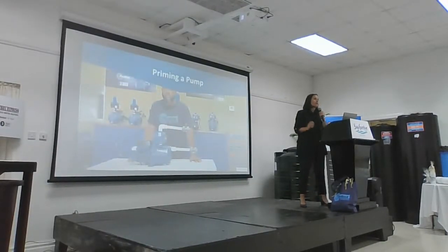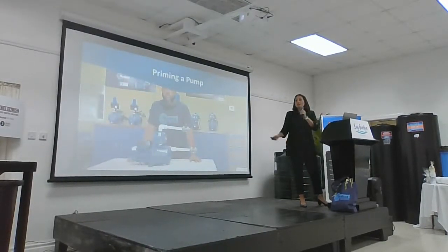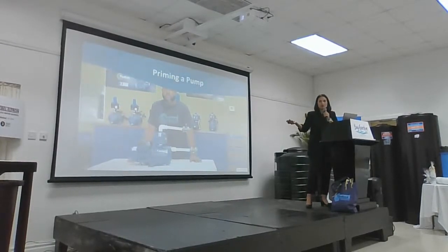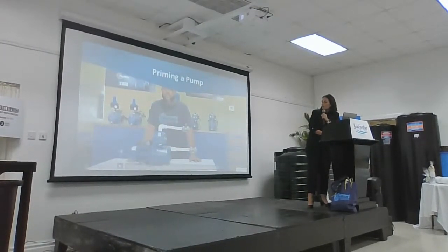So of course, with every new pump installation, it is absolutely essential that you prime the pump. If you don't, this would lead to dry run operation and pump burnouts. So we're going to watch a tutorial on how to prime your pump.